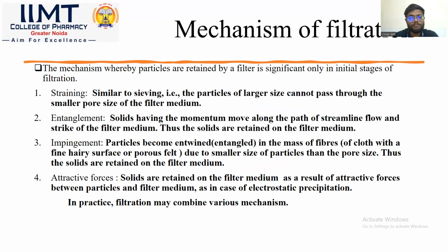Solids having momentum move along the path of streamline flow and strike the filter medium. Thus, the solids are retained on the filter medium. Third one is impingement. Particles become entangled in the mass of fiber of cloth with a fine hairy surface or porous felt.